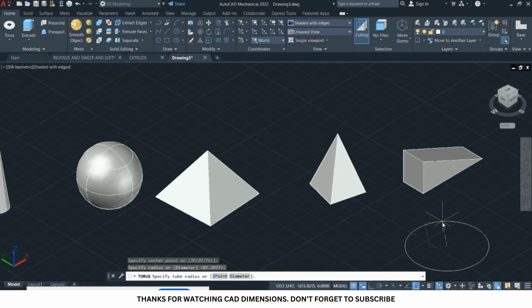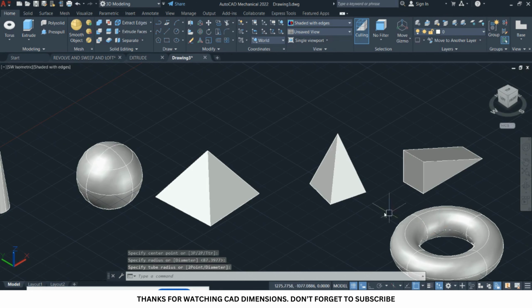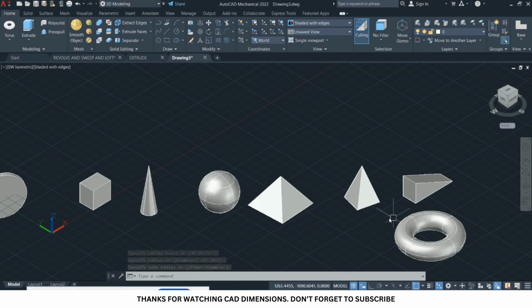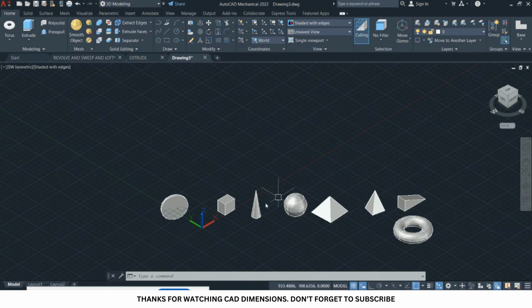Once you are done, you specify the thickness of the circle that you've drawn and it will create a donut shape for you. So guys, that is all about solid primitives. All right, these are preloaded solid models that you can use in your 3D modeling learning process.